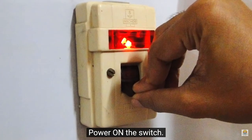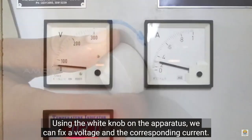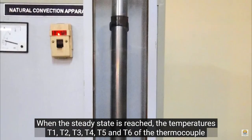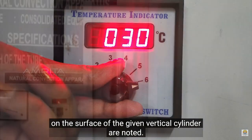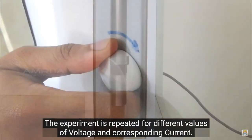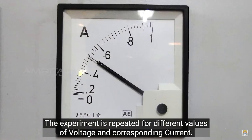Procedure: Power on the switch. Using the white knob on the apparatus, we can fix the voltage and the corresponding current. When the steady state is reached, the temperatures T1, T2, T3, T4, T5 and T6 of the thermocouples on the surface of the given vertical cylinder are noted. The experiment is repeated for different values of voltage and the corresponding current.